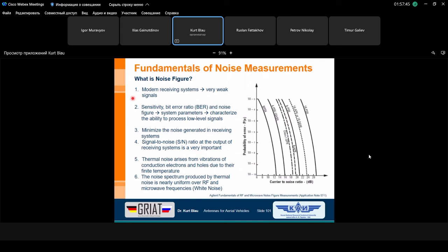So if the wished signal from the transmitter is shut down, switched off, then in most cases people think that at the output of the receiver there's no signal. It's not true. We have a signal. This signal is the noise. It's the noise coming from outside, received by the antenna, and then we have additional noise coming from the active elements, for instance from our transistors.